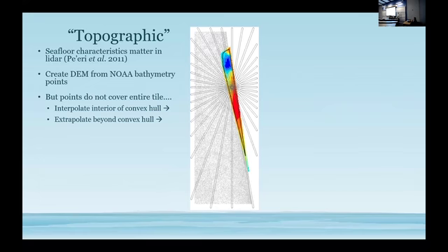I haven't really lost anything. So what I do for that extrapolation is throw spokes out there, trying to get an estimate of elevation there, and there, and there, and there, because once I can get an estimate of elevation outside of the entire tile, I can then go in, re-interpolate, and start filling that in.